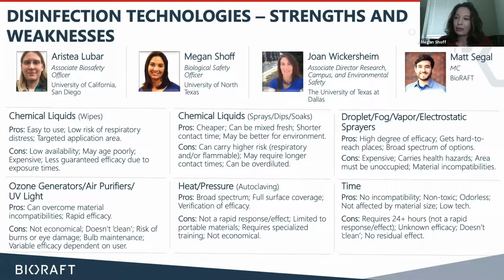there are so many problems with UV disinfection. Does UV kill coronavirus? Yes, it does. UV does kill lots. Well, okay, kill would be the wrong word for viruses, but it inactivates. But UV works on lots of pathogens, but you have to worry about light and shadows. You have to worry about distance. You have to be fairly close to the surfaces. You have to worry about energy amounts depending on the pathogen.